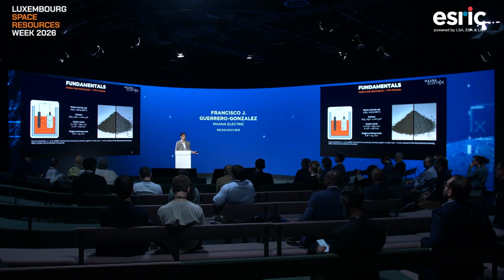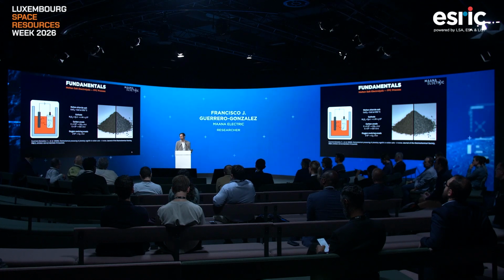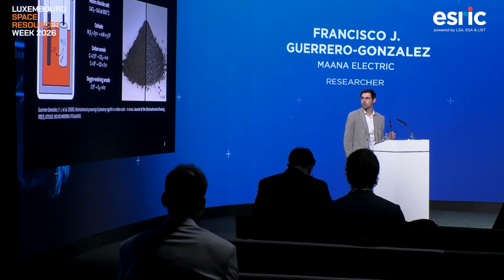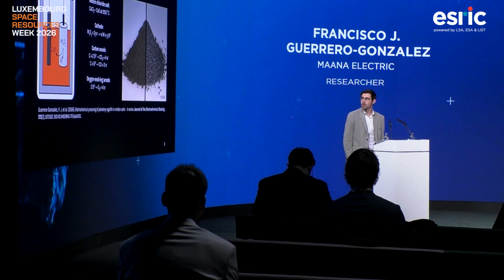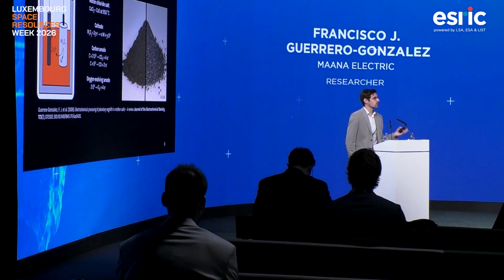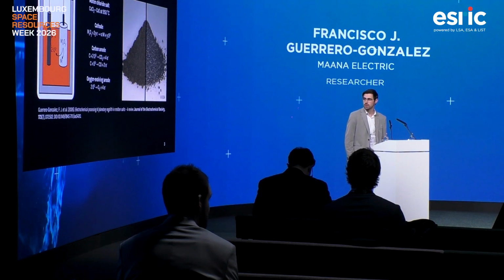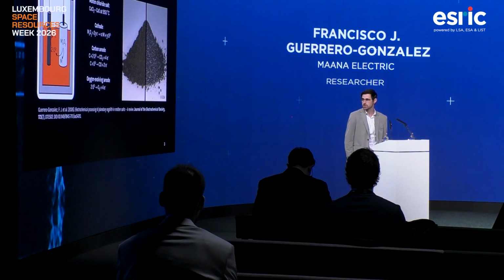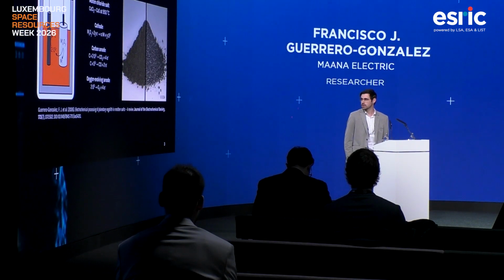In this case, we don't have a membrane. We use a solid material as an oxygen-evolving anode, as an inert anode. That's also one of the things that we are looking into. All this difference between molten chlorides, molten fluorides, we have just published a paper reviewing all of those different processes in the Journal of the Electrochemical Society. So I encourage you to take a look at that, to go a bit deeper into the differences.